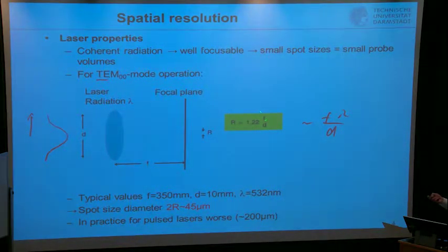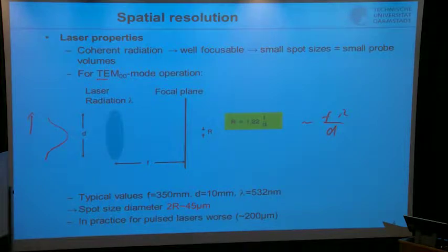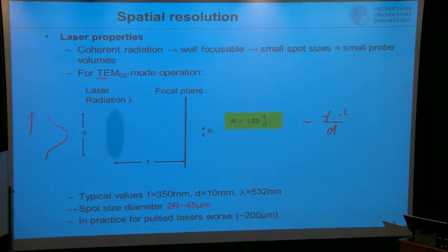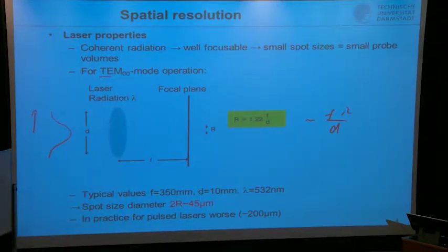What you can more easily vary is the focal length of your last lens, assuming that you have parallel light approaching from the left. And there, of course, your limitation is more from your process. Because you have a hot flame, very often an enclosure, you might not be able to get as close as you wish.